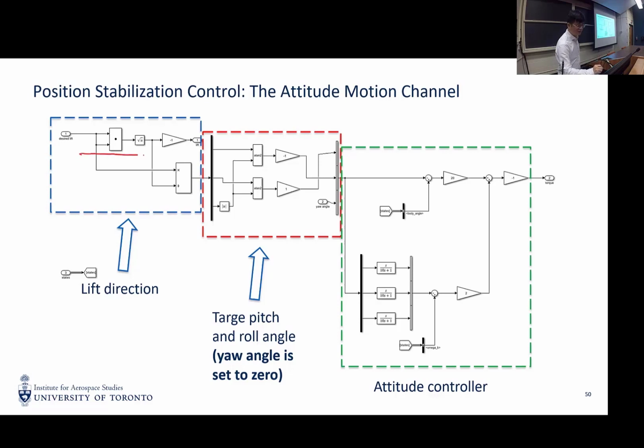So the first step is still to get the magnitude of lift, by doing the dot product and the square root to get the desired rotor lift provided by the 4 rotors. Then by dividing F_d, we get n_d, the desired pointing, so the lift direction of the quadrotor.